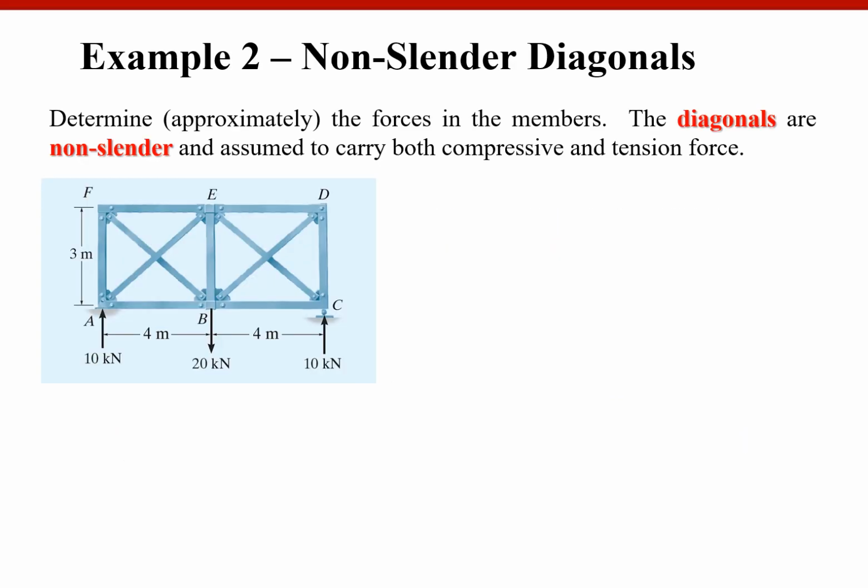All right. In this example, we are going to determine the member forces in the members. Again, I know the member forces will be in either tension or compression. No bending moment, no shear force. And we are going to make a cut there, wherever you need to calculate your member force. And we have member crossing here, so that we know this truss is statically indeterminate structure.